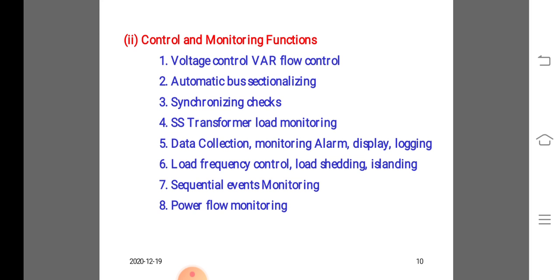Microwave operates at frequencies above 1 GHz. The earlier microwave telemetry was strictly analog, but digital microwave communication is now quite common for EMS SCADA applications. This form of communication has obvious advantages over PLC and leased wire since it requires no physical conducting medium and therefore no right of way. However, line of sight clearance is required in order to ensure reliable communication